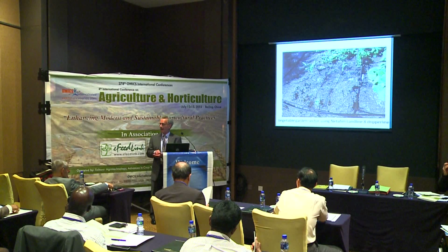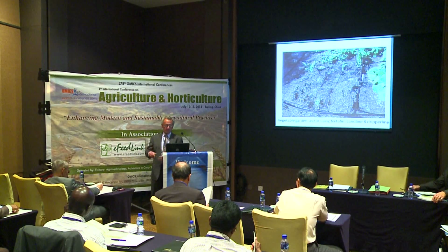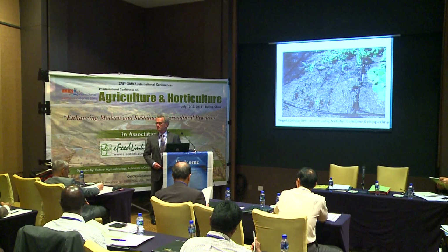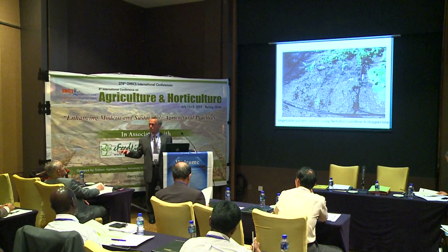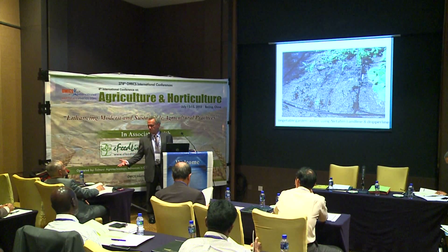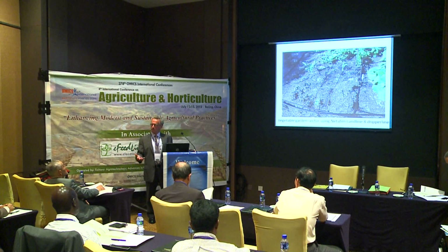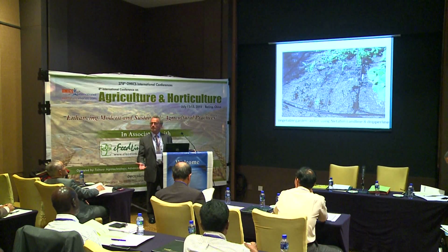It doesn't matter how long it takes, and typically for measured irrigation, the irrigation event might last 4 or 5 hours. It'd be very slow because of the very low pressure. But that's not a problem because you still get the correct volume of water delivered to the plants, even though it may take a long time.